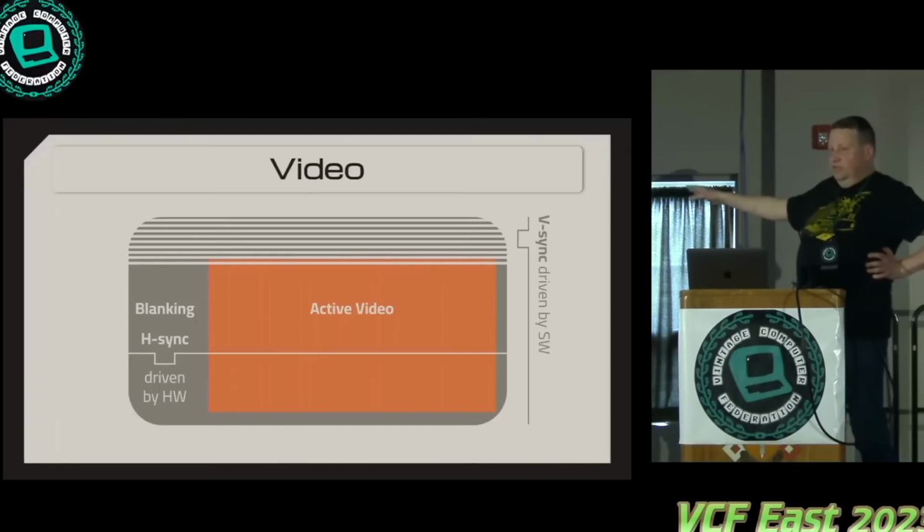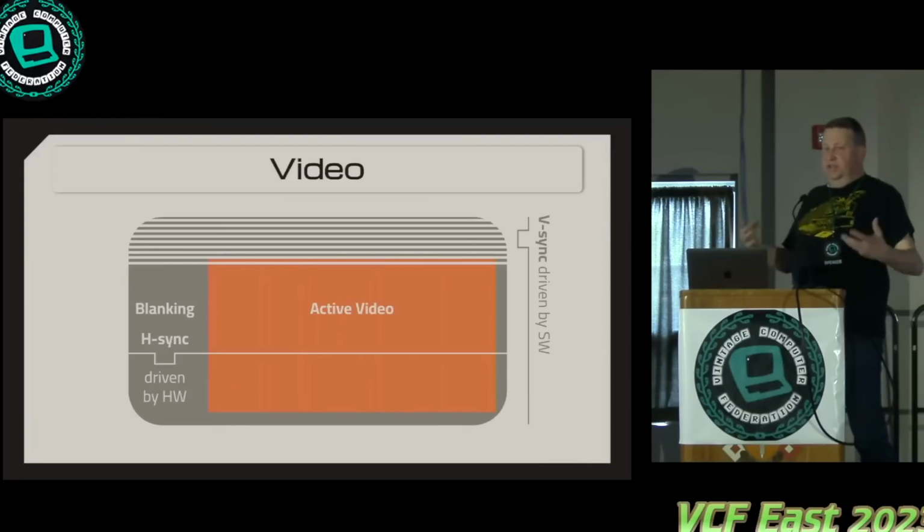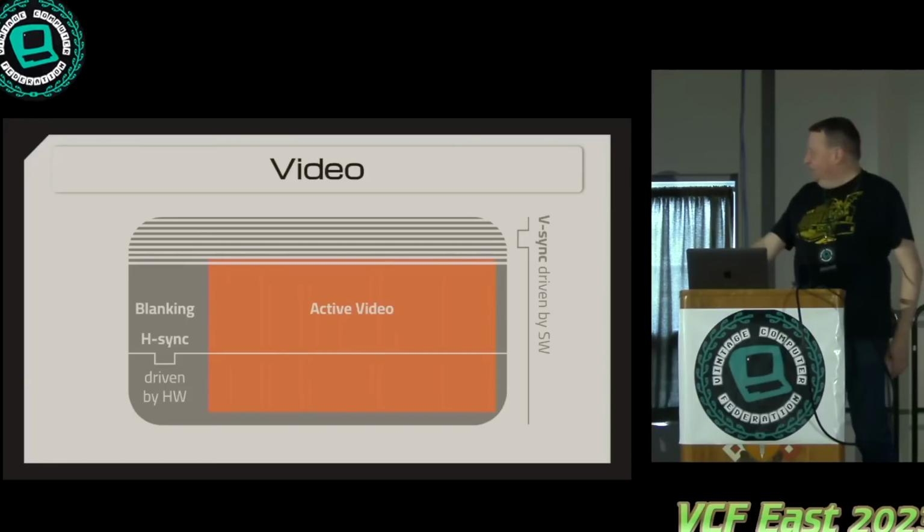So there's a vertical sync pulse and a horizontal sync pulse generated by the machine, and that tells a monitor all the information it gets about what's happening in terms of timing. So whether it's when to start the line, when to start the next frame. And there's some blanking. I don't really do the blanking. The blanking's done just by writing a bunch of zeros to the memory, so it doesn't output anything. There isn't a lot of logic to do that.